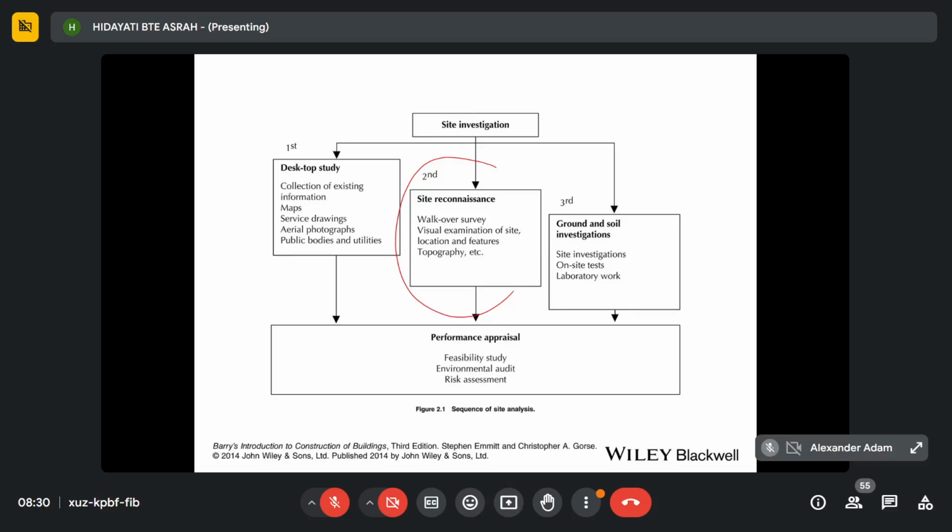So when you do the visual inspection, you can observe the condition of the subsoil on your site project, vegetation, if there is marshy ground, signs of groundwater or flooding. You can also observe if there is irregular topography or if there is ground erosion and so on. Photographic and video surveys are also very helpful. You need to have a record of the original condition of the site. So you can do video recording, in case of any dispute or claim for damage. It is actually a proof for you.